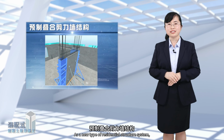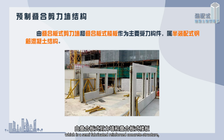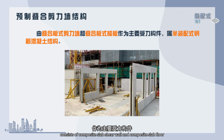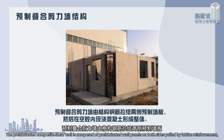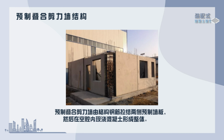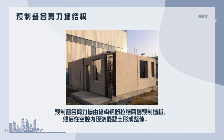As a new type of residential structure system, the precast composite shear wall structure, which is a semi-fabricated reinforced concrete structure, consists of composite slab shear walls and composite slab floors as the main stress components. The prefabricated composite shear wall is composed of prefabricated wall panels on both sides connected by lattice reinforcement, and then concrete is cast in situ in the cavity to form a whole.